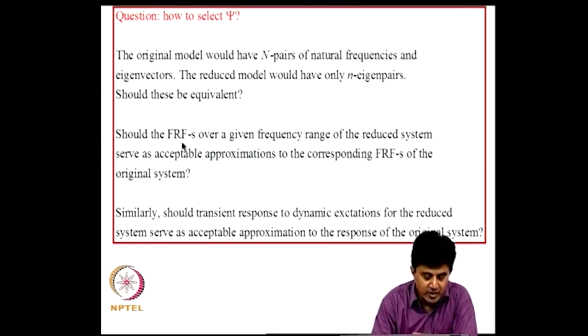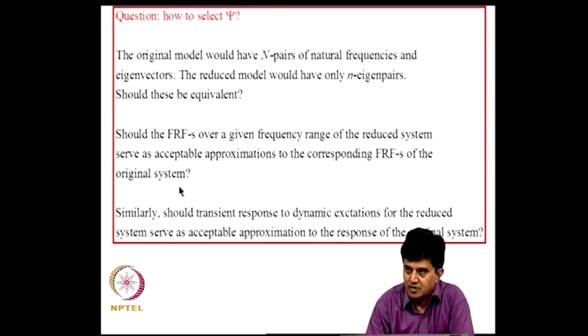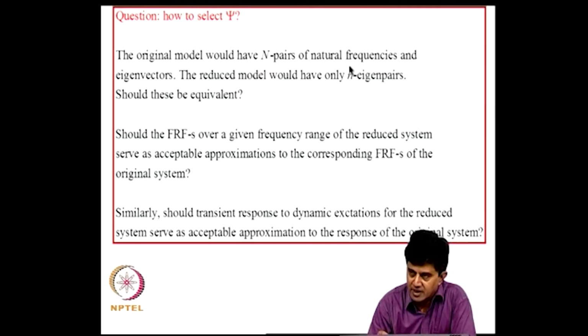Or should the frequency response function over a given frequency range of the reduced system serve as an acceptable approximation to the corresponding FRFs of the original system? So, here we are matching response, here we are matching only the natural frequency. So, if we match FRFs, the issues related to mode shapes as well as damping models would be allowed for.